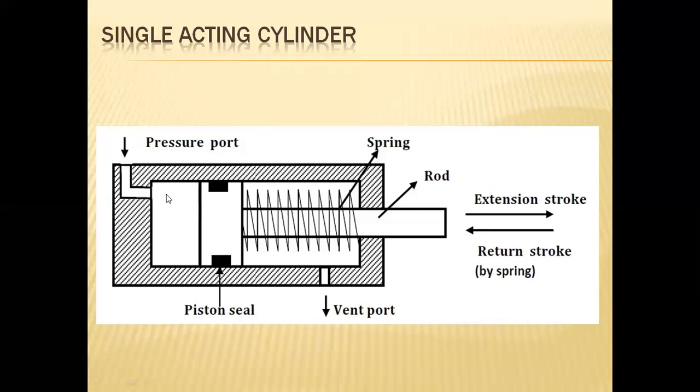And when the additional pressure maintained to move the piston towards the forward stroke or extension stroke is halted or reduced, or equals the tension in the spring, or is less than the tension existing within the spring, simultaneously the forward movement will get stopped. And when a complete extension in the forward stroke has been commenced, we will observe the full spring tension existing here.